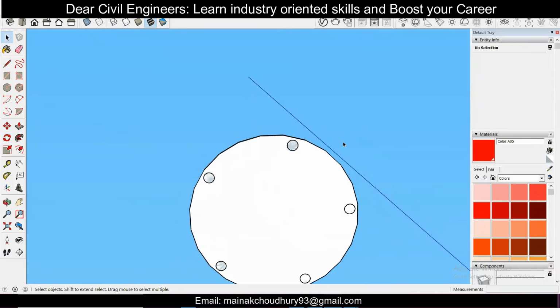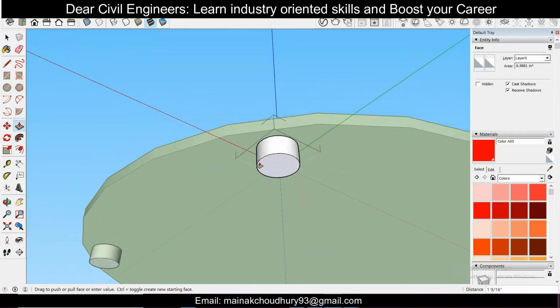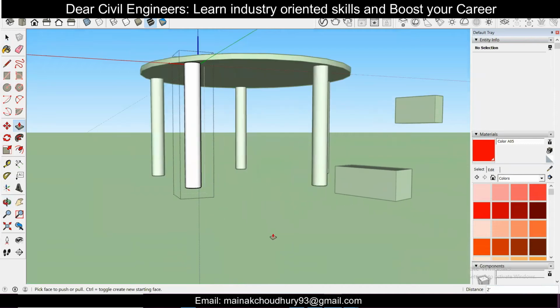And after these components are made, just select this and double click this, and after that use the push pull tool to give it a particular height. Let me give it a height of, let's say, 2 feet, enter. And then you can see here this table has been made.